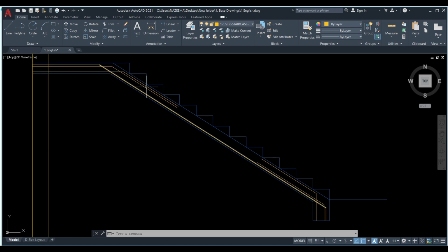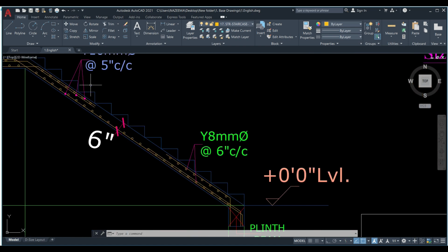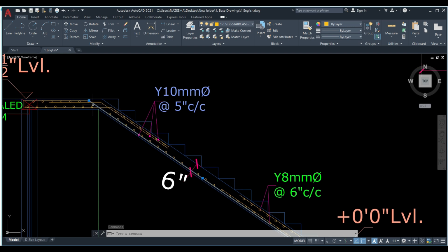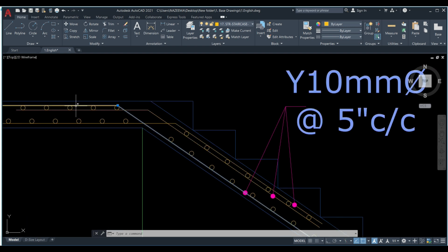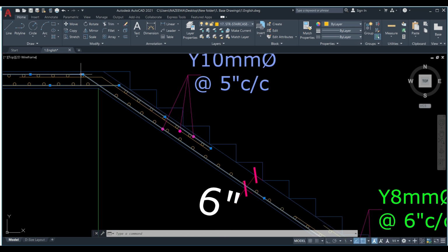Okay, so please watch this class 2 to 3 times and you will get a good handle of how to draw this particular staircase. First you have to draw the shape of the staircase. Once the shape is done, you will draw the mid landing, whatever the reinforcement is required, take that and you go to the mid landing portion and you terminate the bar over here. So the bottom rebar becomes a top rebar, followed by you go for this and you repeat those steps again. Okay, whatever the offset is, you take offset from here, you take offset from here, and you create a rebar like that. So we get a crisscross arrangement on top.